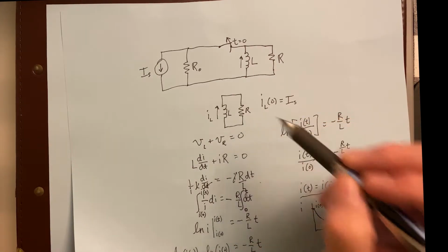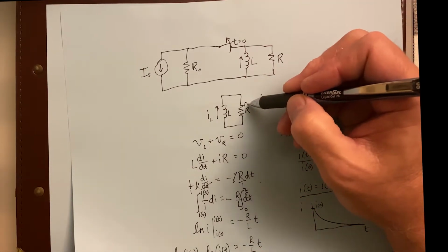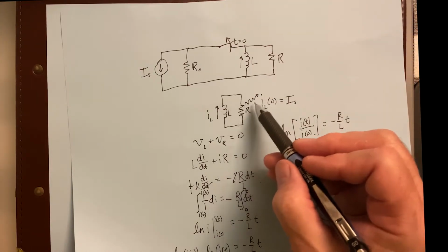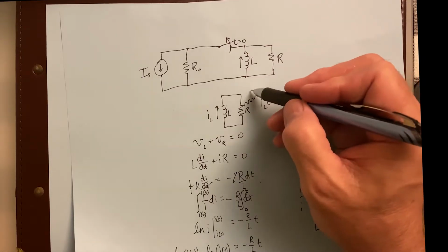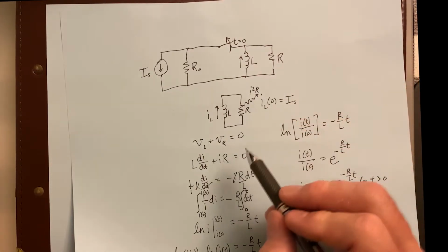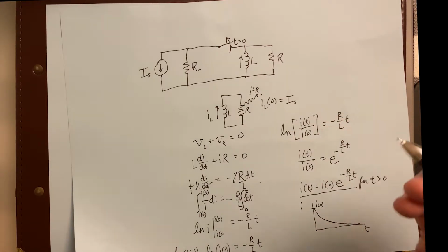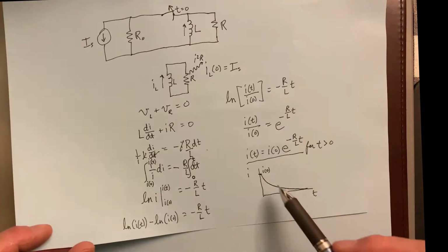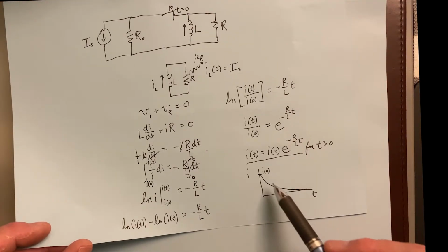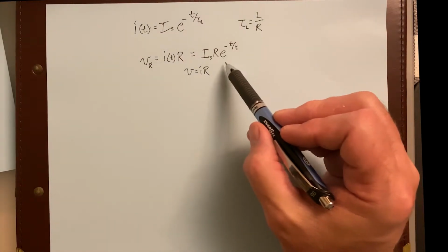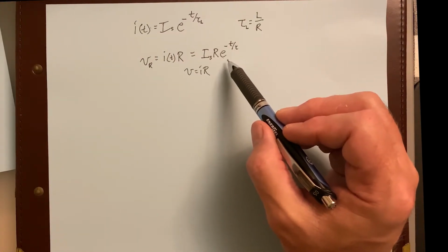But as the current passes through the resistor, it's going to heat up and it's going to dissipate energy in the form of radiation at a rate of I squared R. So that's the energy that's leaving the system. So energy that's leaving the system is what's causing this decay to occur for the current, and it's what's also causing the voltage to vary over time.